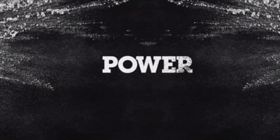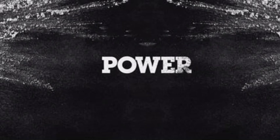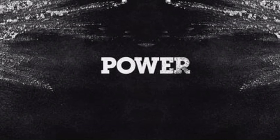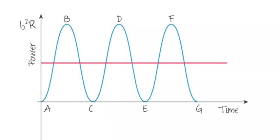As for the power made in this process, this is measured in average power. Average power is easy to calculate in direct current, as the current is constant, but in alternating current, as its name states, the current varies by time. To get a grasp of how the power is generated by alternating current, we should use the formula power is equal to current squared times resistance. As the resistance is a constant, the current squared will result in a squared sine graph.